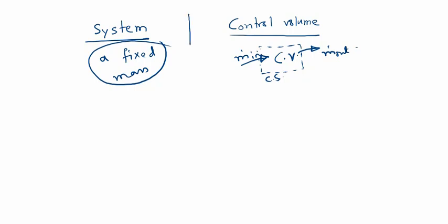In the heat transfer course or the fluid mechanics course, we generally do not use the term closed. So whenever we write system, remember that it means a closed system. That is always implied. To represent the open system, we always use the term control volume; we never use the term system for it. System means a fixed mass, that is, the closed system. I am not going to repeat this whenever we use it afterwards.